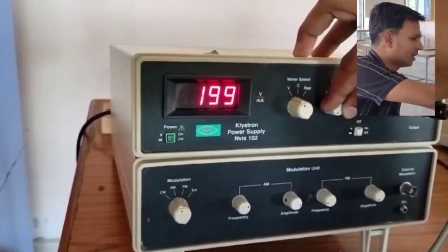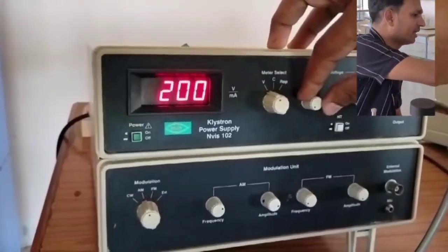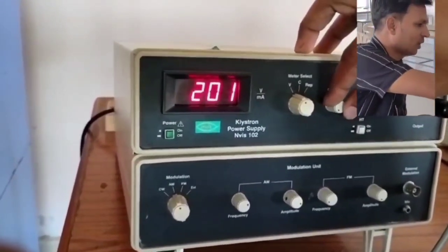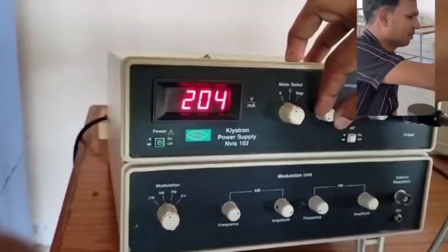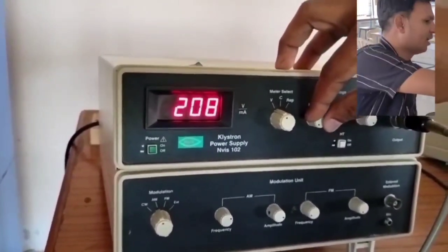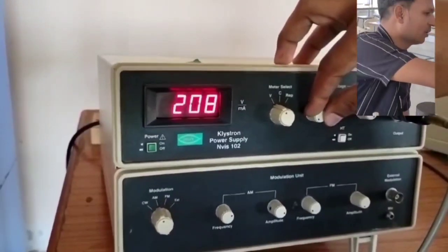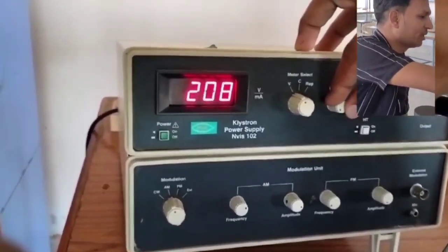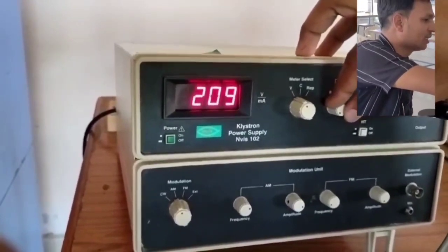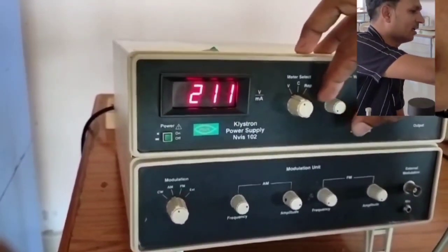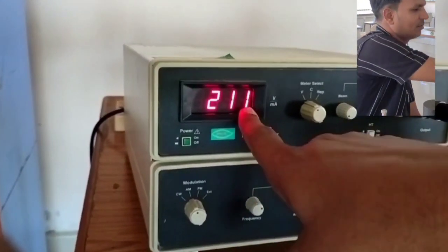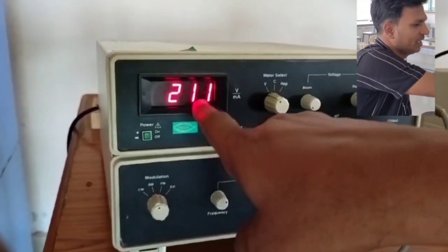See here, everyone, I am varying it slowly. While varying, the values also vary. See the display, every one of you. While you are doing this experiment in your college laboratory, you have to vary slowly. Then it will be very useful. If you unknowingly give more voltage, the entire microwave bench setup is going to get damaged. Okay, students, slowly I am varying. 210, yes, 211. What is the beam voltage now? In your observation and lab record, you have to note that the beam voltage is 210.